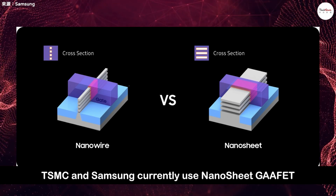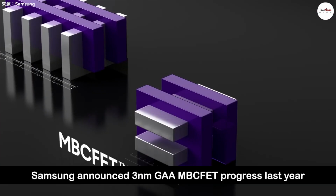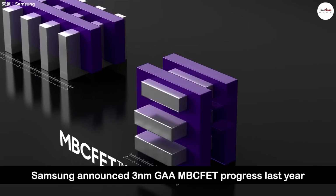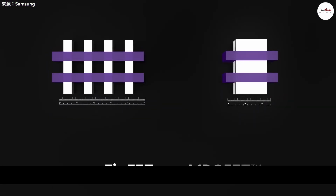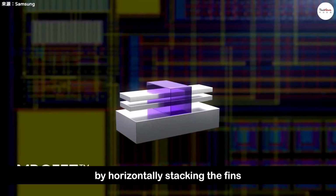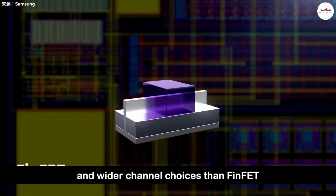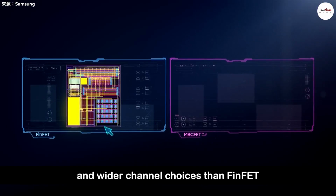TSMC and Samsung currently use nanosheet GAAFET. Samsung announced 3 nanometer GAA MBC FET progress last year. MBC FET offers better design flexibility by horizontally stacking the fins. It allows free adjustment of nanosheet height and wider channel choices than FinFET.